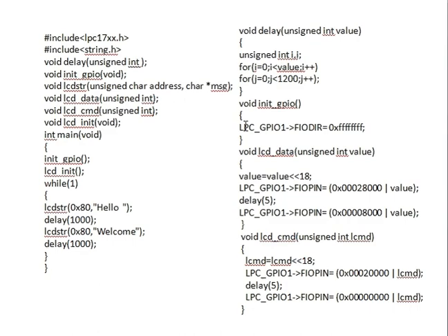So when you call the LCD data function, this program is getting executed. I just repeat, the job is you have to differentiate whether you are sending data or sending commands, and for that we have port 1 pin 15, and that should be made high now. That is to ensure that you're sending data onto the LCD.